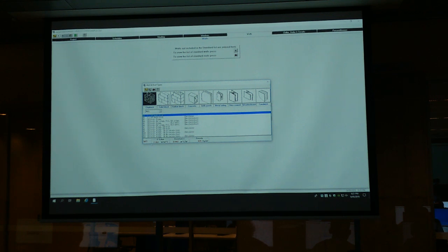On the bottom, you can see all the properties: U value, resistance, and the density. Please notice the density here is not based on volume, it's based on the area. And there are different walls: clay brick, solid brick, and different structures, concrete, fibro, weatherboard, sandwich, whatever. You need to choose from this menu for the wall given in the project.